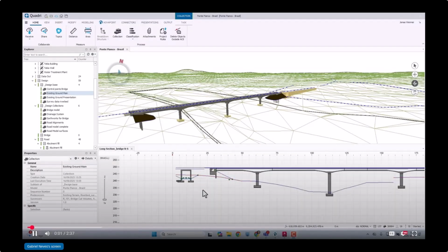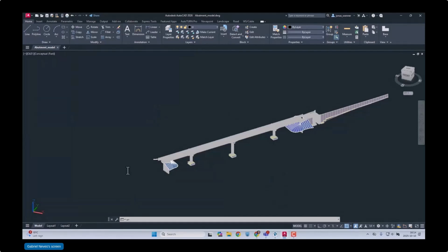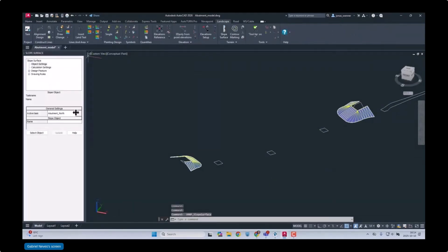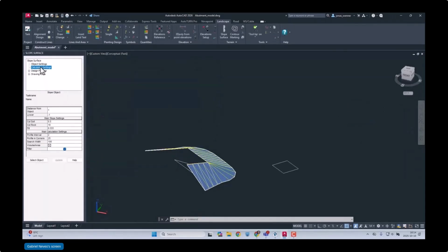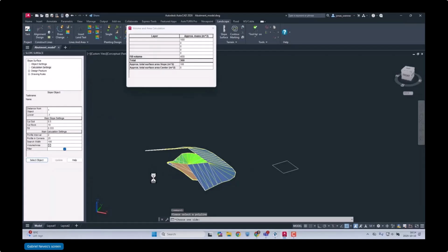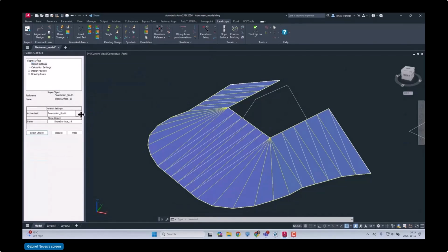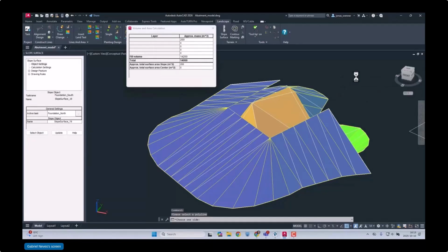And we can make this with the same functionality as we used for the fills at the end of the bridge. So in this case, we just create 3D polylines as well at the soles here, and then we can tell the system that it should offset these lines 1 meter from the line and place it 1 meter below, for example, to make the excavation pit a little bit larger and deeper than the sole of the bridge.